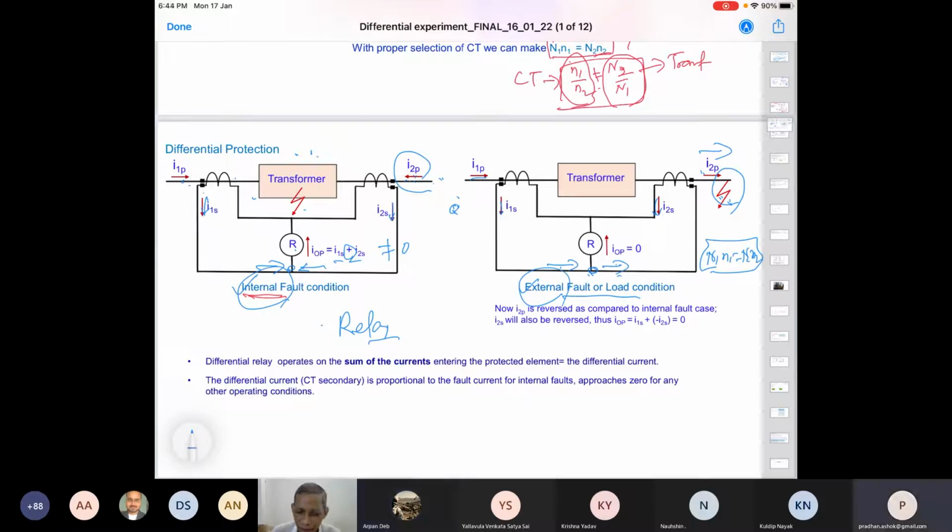Very right. You are able to judge the internal fault, true, because the differential current is significant. So it will be above a threshold, simply in terms of the current perspective. Then the internal fault is clearly identified. Your question is that for an external fault you don't know. It is not possible. Not required. Why not required? This relay setup is to take care of this transformer only. Really, I don't bother about what others are happening. So this is the philosophy here.